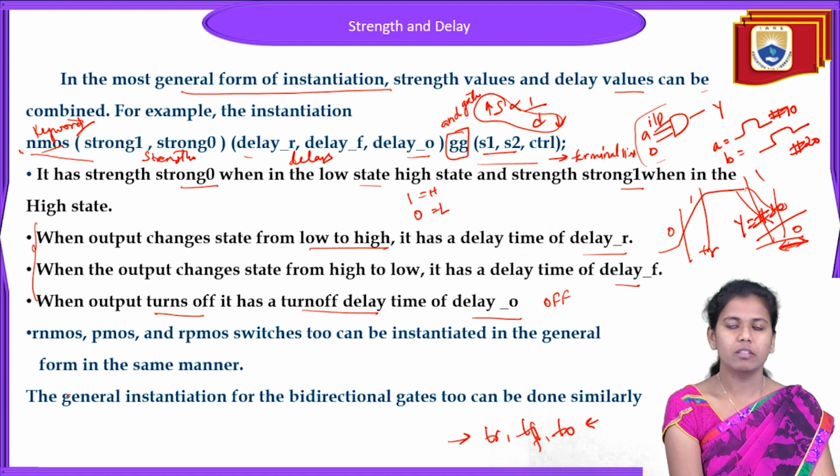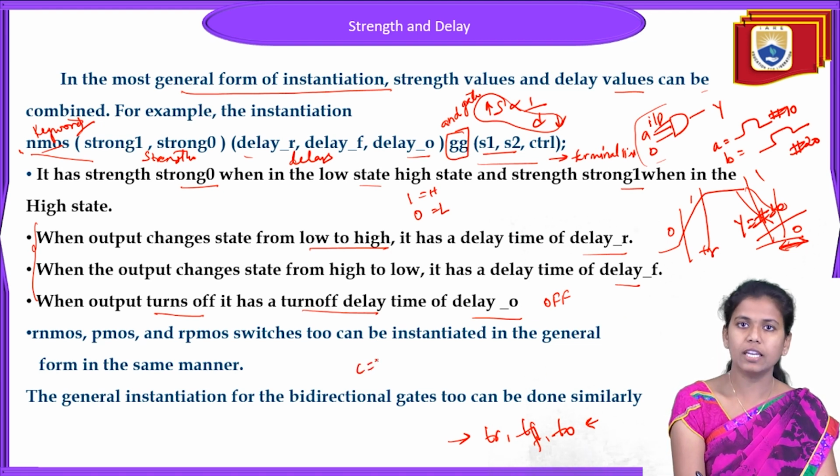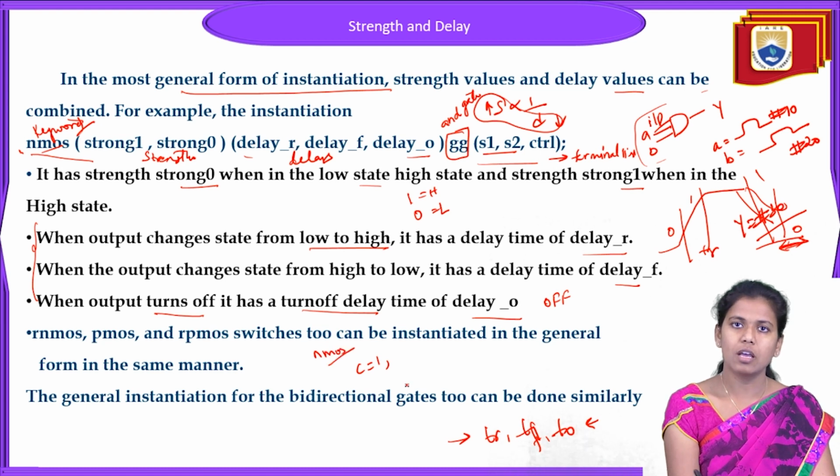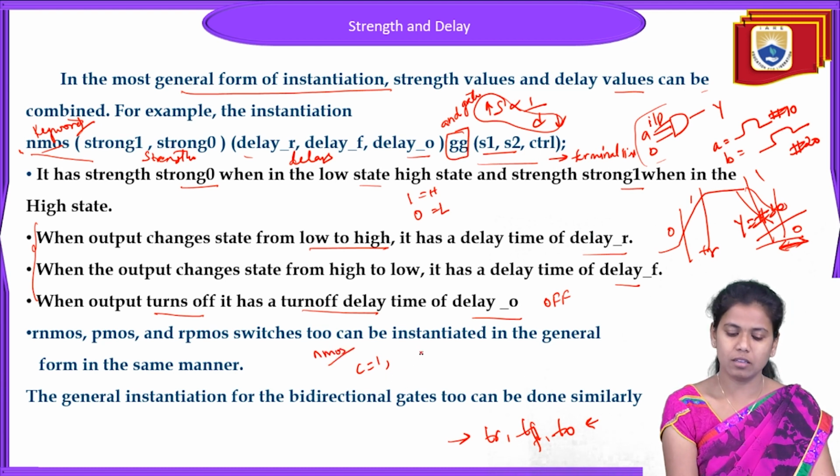Okay. And then in the previous section we have already discussed the NMOS, PMOS and CMOS switches. The switching conditions of NMOS and PMOS are quite in contrast to each other. That means, in the NMOS transistor, when the control signal is 1, the switch goes to on condition, and if the control signal is 0, then obviously the switch goes to off condition.